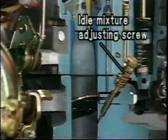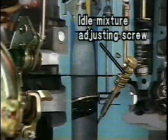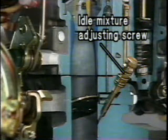The idle port is supplied with an idle mixture adjusting screw to allow the idle air-fuel ratio to be adjusted. The mixture can be made richer while the engine is idling.